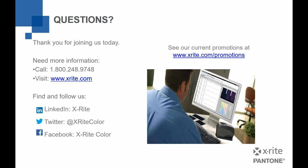In the mass system that we have, which is called a multiflux mass system, we're going to pick our calibrating resin. So that's what we're going to make all our mixtures in. We also can have alternate resins. Alternate resins means I can use these same pigments, but it's a different resin than the calibrating resin. We would make 100% of that resin, and then generally we're going to have a couple mixes of white, a couple mixes of black, and then a couple grays. So you're generally going to have 6 to 7 samples, but one sample would be 100%.